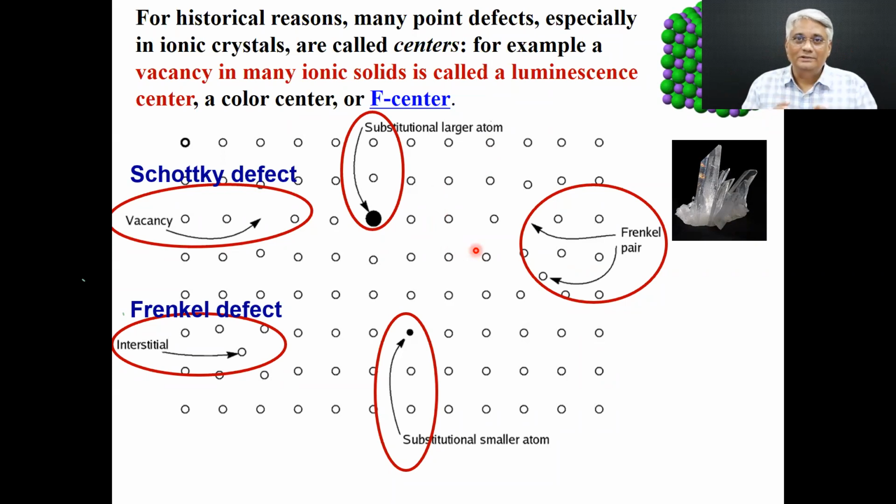Nitrogen replacing carbon, like boron replaces silicon in silicon lattice, brings about some additional carriers into the lattice. It can transform even this insulating diamond into a good conductor. And with boron doping, it becomes even superconducting. But nitrogen doping can have many positive implications.